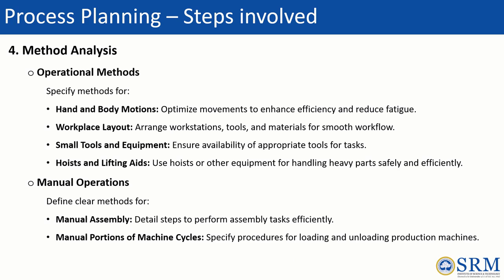Coming to the method analysis, the method analysis focuses on improving operational efficiency. This includes optimizing the worker movements, workplace layout, tool placement and material handling systems. For manual operations, clear procedures are established for assembly, loading and unloading activities. The objective is to reduce unnecessary motion, improve ergonomics and increase productivity.